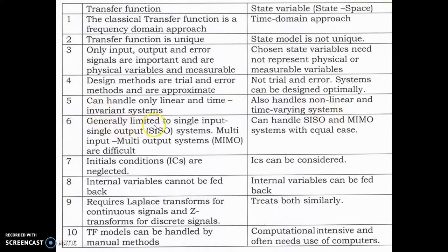Generally, the transfer function method is limited to single input, single output systems. Multi-input, multi-output systems are difficult using the transfer function approach. But in the case of state space analysis, it is very easy to handle both single input, single output, and multi-input, multi-output systems.